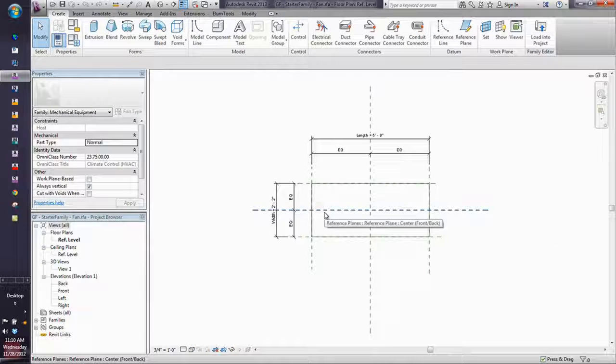And in this particular case, we didn't create it as a family template. What's the difference in making something as a family template as opposed to making something as a family? What happens when you create something like this as a family template? It locks things on you. It locks these parameters down. So rather than having a whole bunch of Revit templates, we actually made a whole bunch of Revit family files.